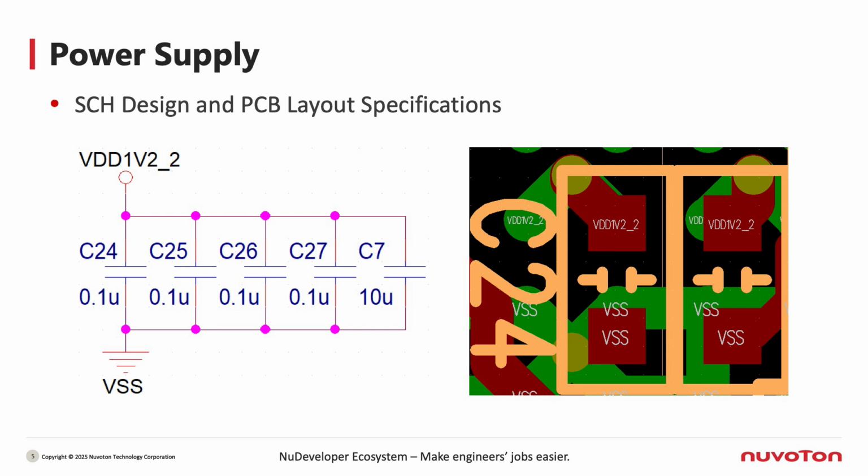In schematic design and PCB layout, there are certain specifications that should be adhered to as much as possible to avoid instability in the board operation due to arbitrary design practices. Therefore, we should ensure that for each set of VDD and GND corresponding to a chip in the schematic design, at least one 104P capacitor is placed. The recommended capacitor materials are X5R or preferably X7R. During layout, each capacitor should be placed as close as possible to its corresponding chip power pin.